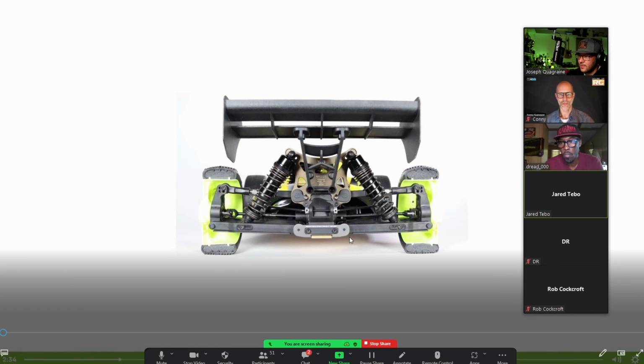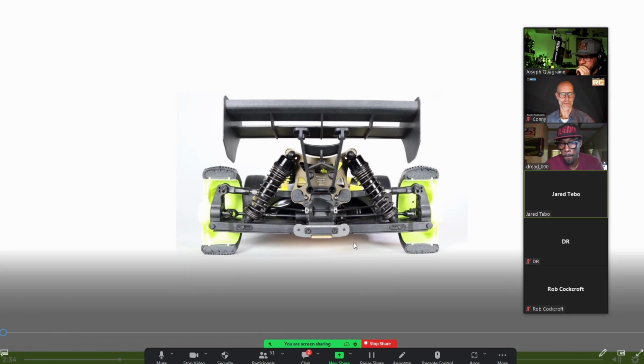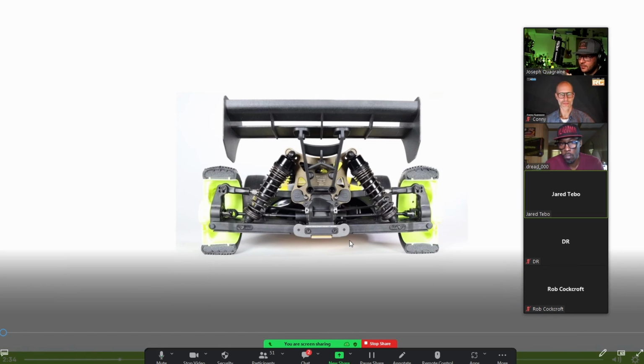Could I jump in real quick and ask you something there, Joseph? Right there, you say softer in roll, stiffer in roll. I feel like that is a poor term as far as our cars, because if you're at a track and you say my car is loose, and someone says okay, this is going to soften the roll, most people are going to think that's going to generate grip. But if you lower your arm, you're going to have less pressure on the tires and your car is going to generate less grip. That's why I have a hard time thinking about it as more or less roll.